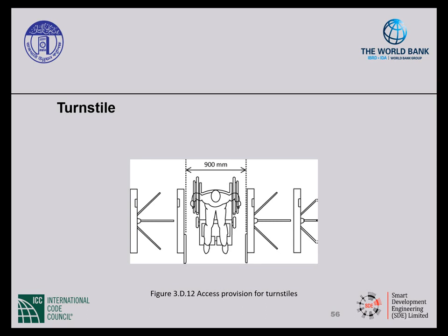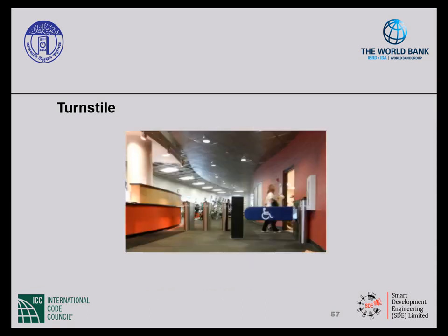You would also locate a gate or a door alongside a revolving door. And note that this is not a one-for-one gate to turnstile. You may locate a gate or a door at each grouping of turnstile or revolving door. And here is an example where you have an accessible gate that's located adjacent to 3 turnstiles.